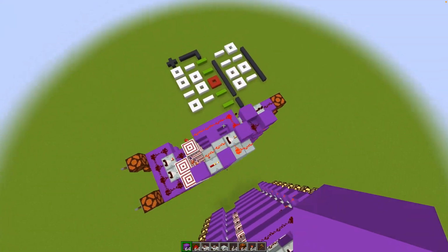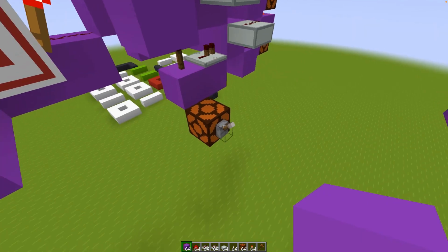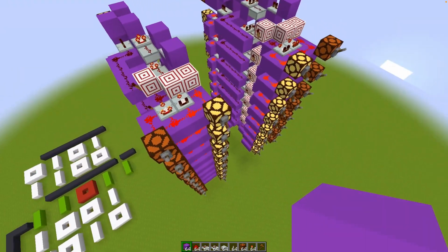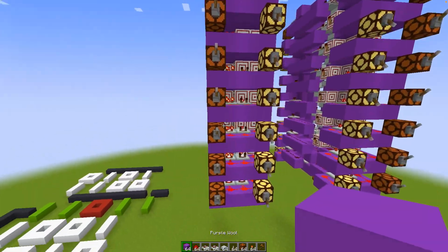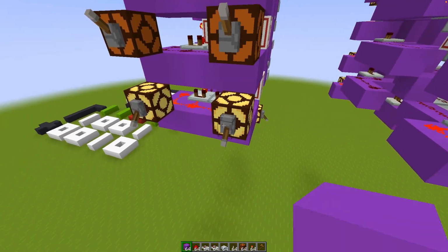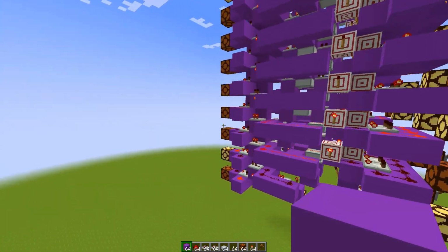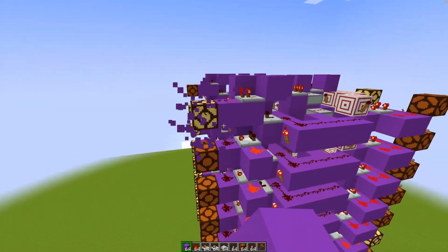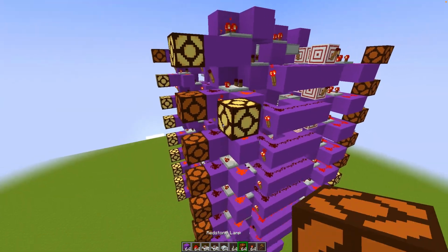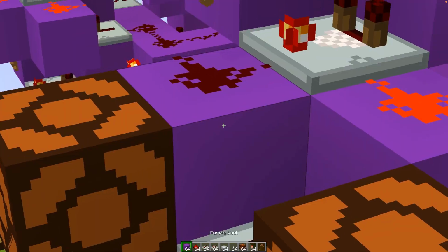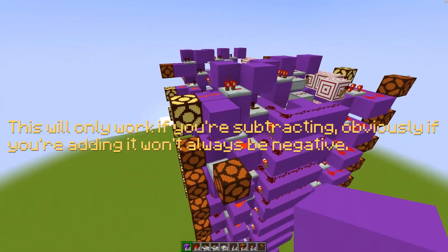And if you want to do subtraction, you just have to turn on the carry in. Invert all of these, which we will just simulate by turning them all on. And after that, let's do 5 by turning on these. And then we put in 3 just by turning them off. So this will be 3. And that is 2, and it's positive because the overflow bit is on. Now we can also check if it's negative by just inverting it. No, not inverting it, by actually just powering it from this bit, not from this one.